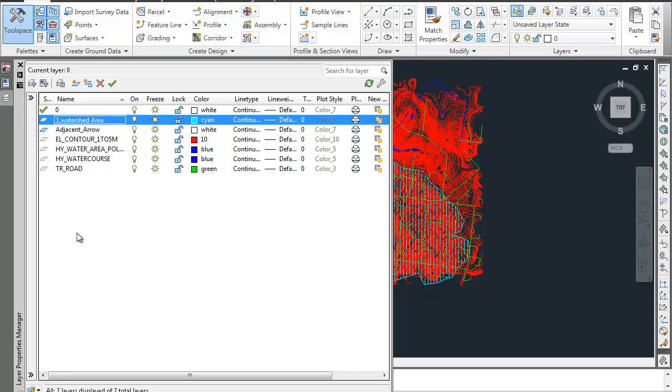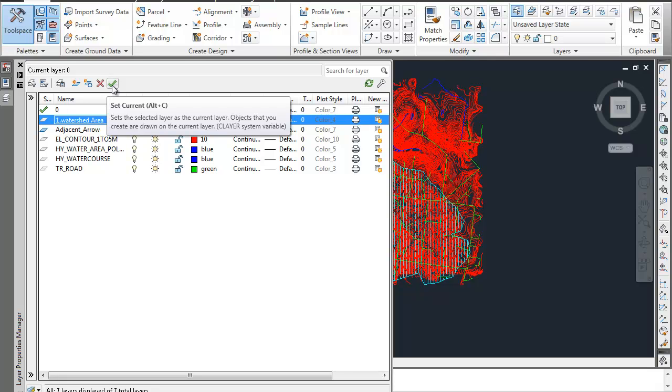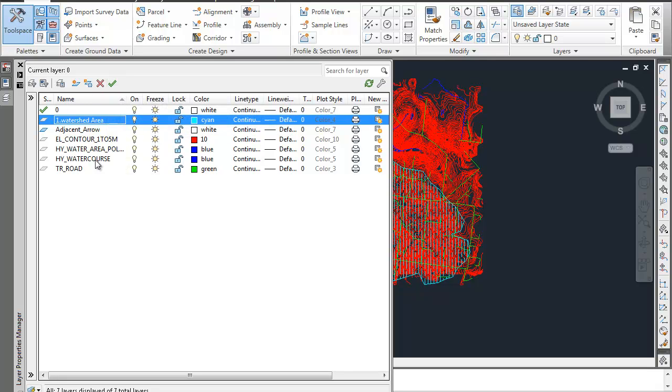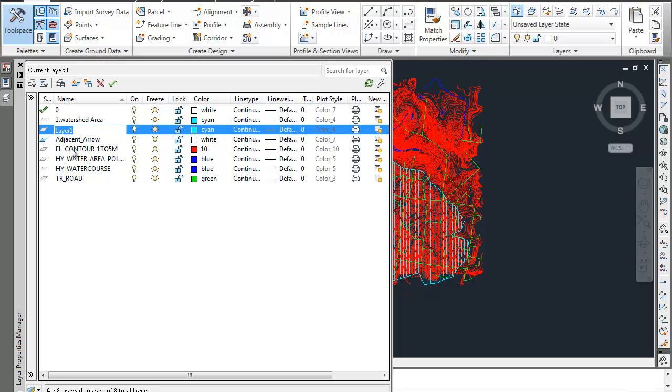All I'm going to do is add some new layers at this point in time because we're already here. The new layers that we are going to add are a notes layer, a water layer, and a viewport layer, because we will need those later on in this exercise. So add new. Because we'd already clicked on the watershed layer, it's going to come up under our default. This one's going to be 2, and this one's going to be water.